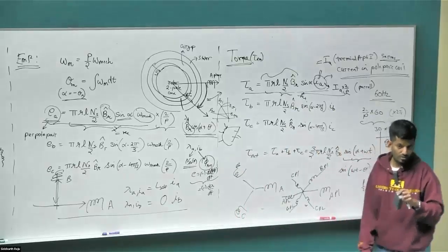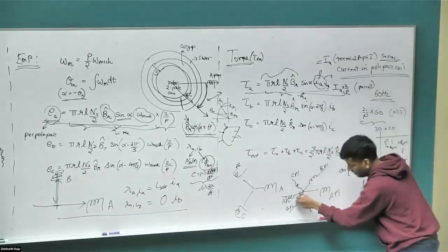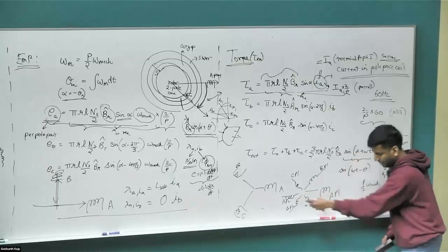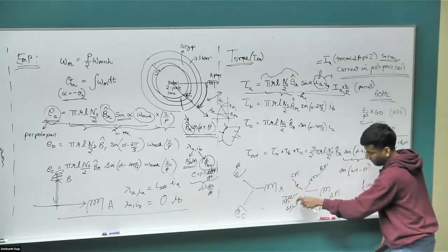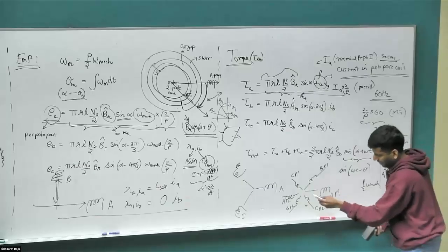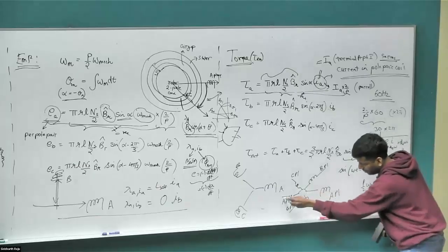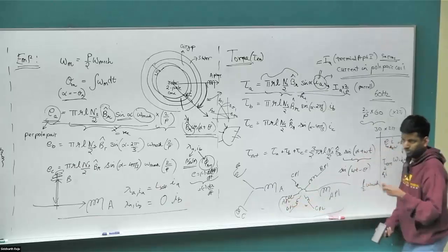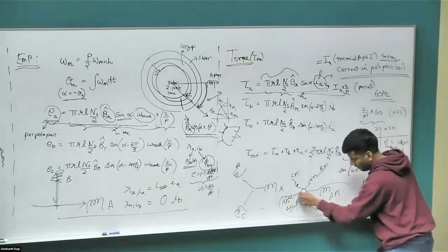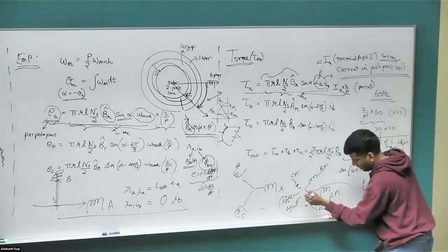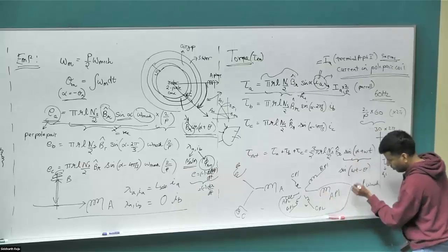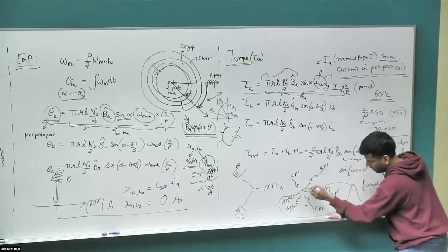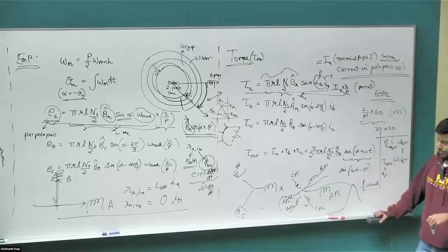But does that drawing you drew like? Oh no, these are not connected. Okay, this is a separate set of coils. This is a separate set of coils. Right, and then the way you would connect them is to connect these two together and get these terminals out. That will be connected in series. If you're doing it in parallel, connect these two together, bring it as one terminal. These two together, bring it as the other terminal. Okay, that makes sense. Thank you.